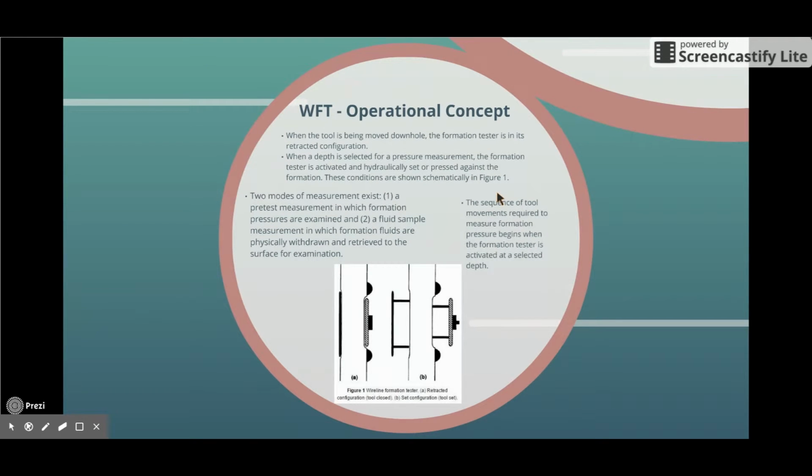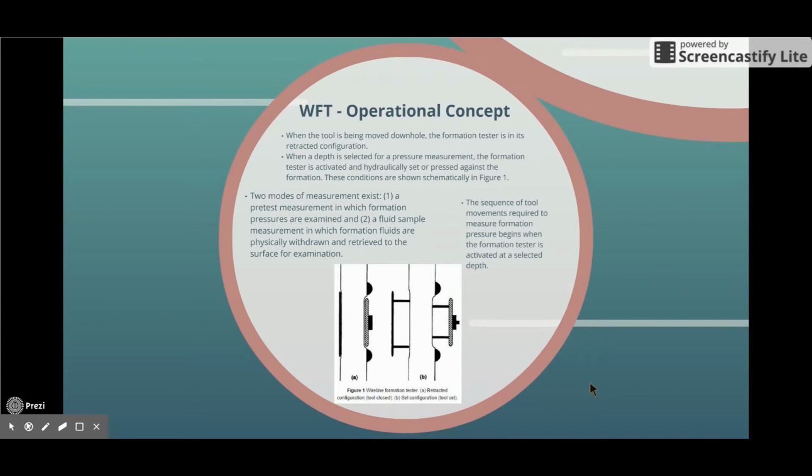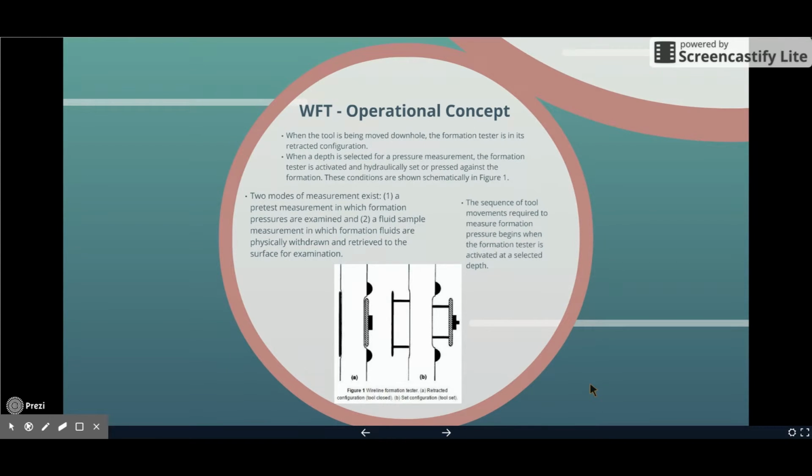Two modes of measurement exist. First, a pre-test measurement in which formation pressures are examined, and second, a fluid sample measurement in which formation fluids are physically withdrawn and retrieved to the surface for examination.